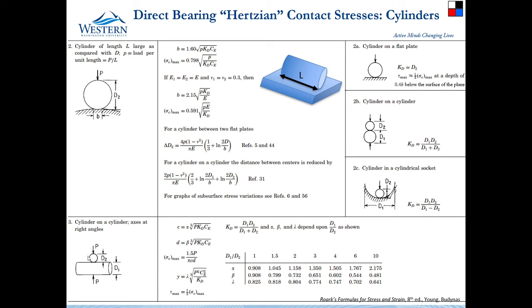This is a really bad case. Don't ever set this up if you can help it. The deflection is just massive in there because you have line contact hitting line contact. So that ends up as being essentially a point, or it becomes a little tiny X and then becomes a little tiny sphere, but with massive loads in this case. So what we're most often going to get here is something like a cylinder lying on its side on a flat,